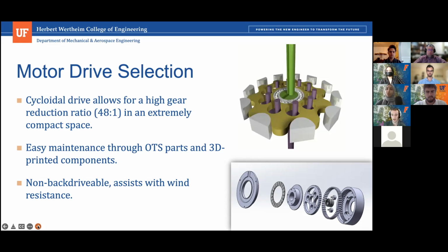Our design has no back drivability, so when you put a force on the gear, there's no give. It utilizes only 3D printed parts and off-the-shelf bearings, and we had the torque extract plate manufactured in metal because that's the part that undergoes the most load and holds the fasteners.